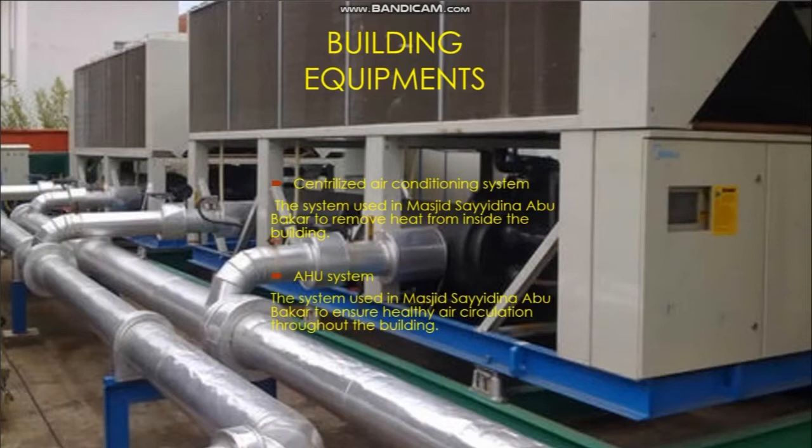There are a few parts in both systems that need to be maintained, such as air filter, condensation pan inside air handling units, and also electrical connection in the system.